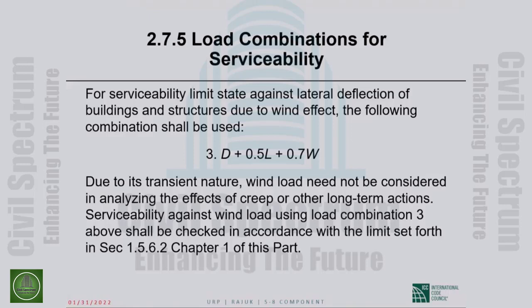Due to its transient nature, wind load need not be considered in analyzing the effects of creep or other long-term actions. So this is just the short-term deflections. It is seldom that gravity loads cause lateral deflections anyway.